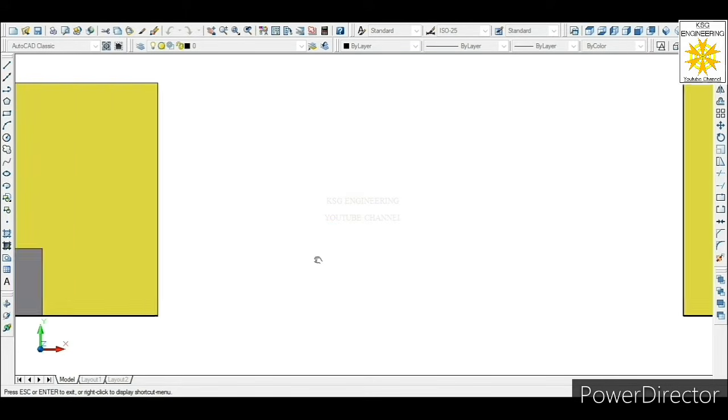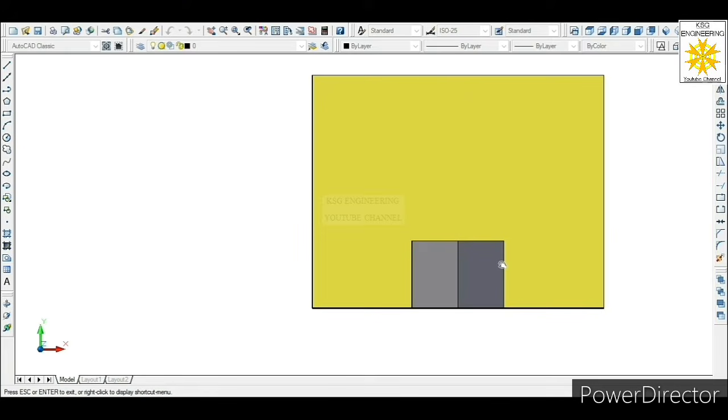But now in the second position, we have rotated the cube at 45 degrees, and you can see now we are able to see two front faces of the cube, and these two are inclined at 45 degrees to the vertical plane. So that's why we see these two faces as reduced faces.